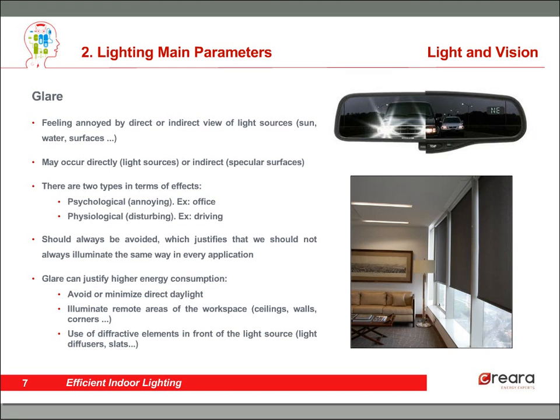First, because we must avoid or at least minimize direct daylight. Second, because we don't have to illuminate directly, we have to illuminate remote areas of the workspace, such as ceilings, walls, corners. And finally, we have to use diffractive elements in front of the light source, like diffusers.